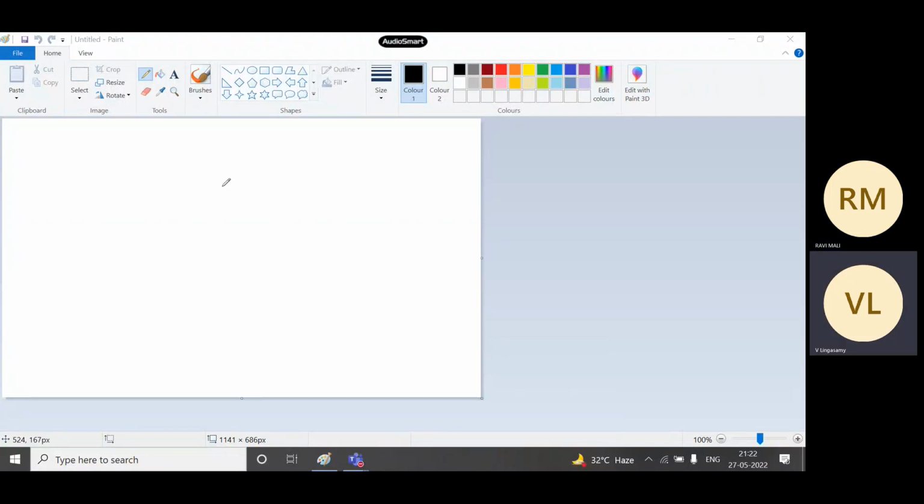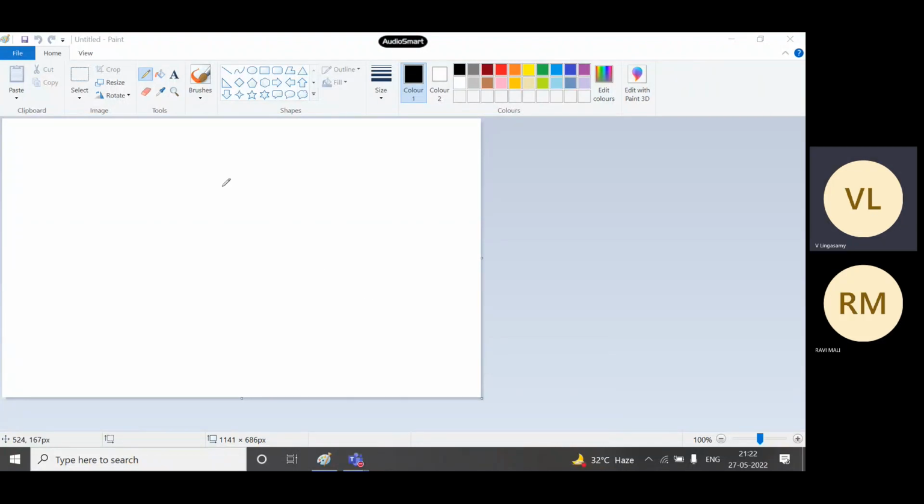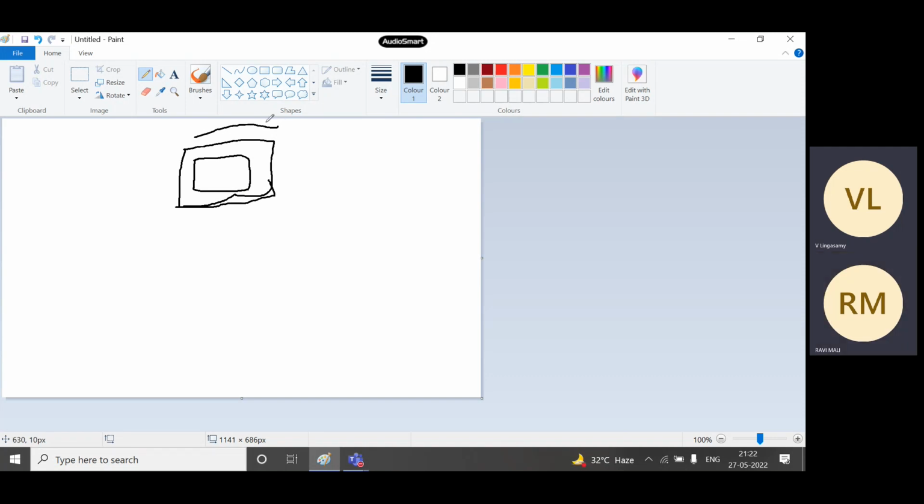Okay, let me tell you from the unit cell perspective and also the array element perspective. From the unit cell perspective, you have some element size, including substrate and ground plane. When you simulate the unit cell, this size should be lambda by 2. This is the substrate size, not the patch size. The patch size will never be lambda by 2, only the unit cell size, which you are keeping as the interelement spacing.